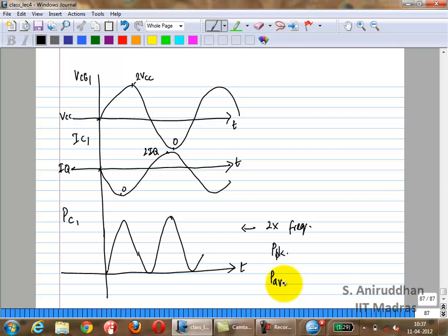What happens if the frequency of operation is very large? What happens? So you will be hitting the peaks only. So what will happen is the average and the peak will move closer to each other. So you will start worrying mainly about the average, not about the peaks. It won't be spending at the peaks enough time for it to heat up the junction appreciably. You are more worried about the average value. Okay?